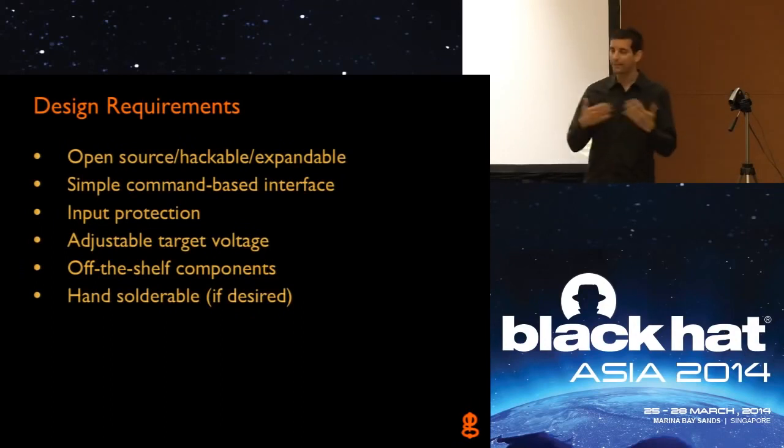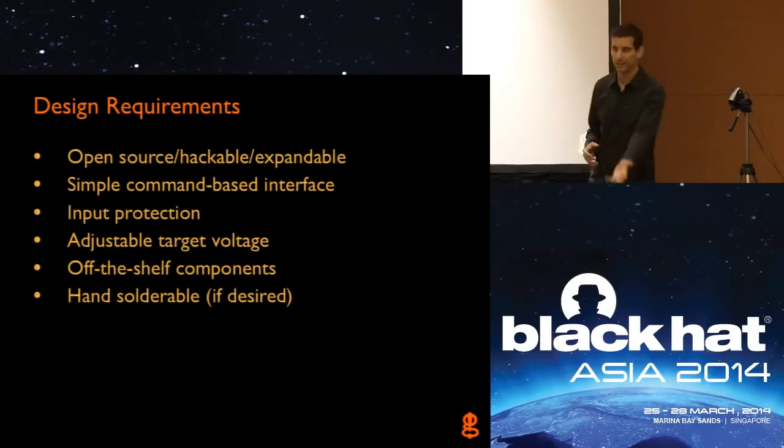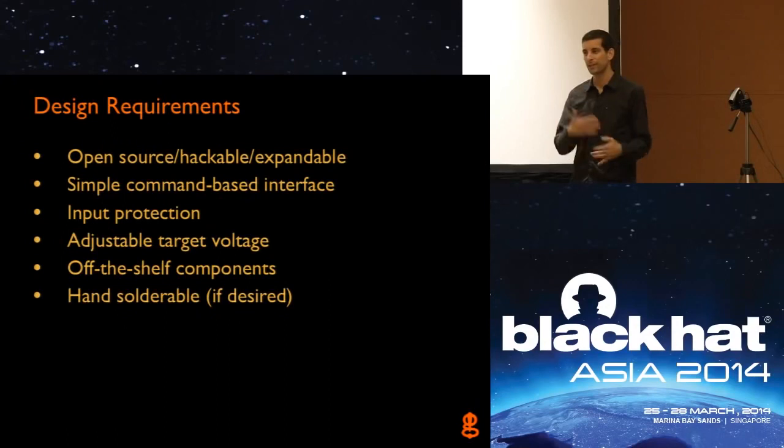So we want to have some sort of way to properly communicate and properly have the levels that we're sending from the JTAGulator meet the specifications of the target board. Because the JTAGulator system is a 3.3 volt system, because that's what the Propeller processor runs on, and that's what we're using. So we need a way to kind of convert that and make sure that we don't damage any signals going out and any signals coming back in.